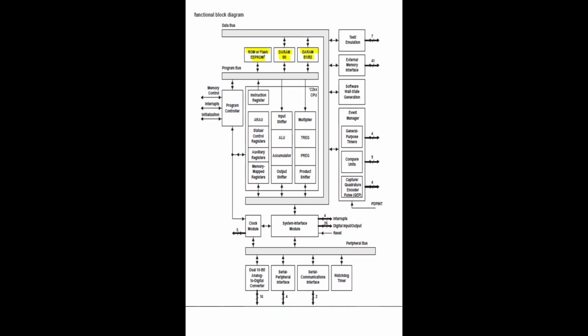used for program space. Program space means, for example, if you want to add two numbers, ADD A comma B, this operation is program space. It takes two numbers, MOV A comma B, moves this data to that register, like that. These are all called the program. This program space will be taken care of by B0 if the CNF bit is 1. I hope you all understood this memory part.